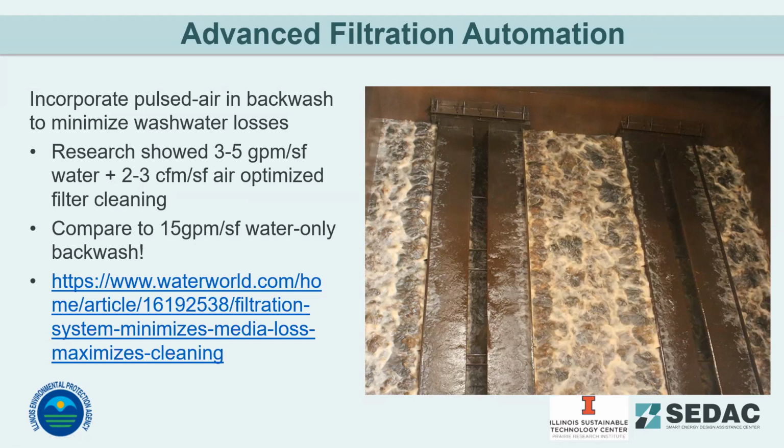So with the advanced filtration automation, you can use the PLC controls to maintain the backwash flow through the valve position or the pump VFD speed at a lower rate during air scour, then increase to the standard rates during the restratification settling phase.